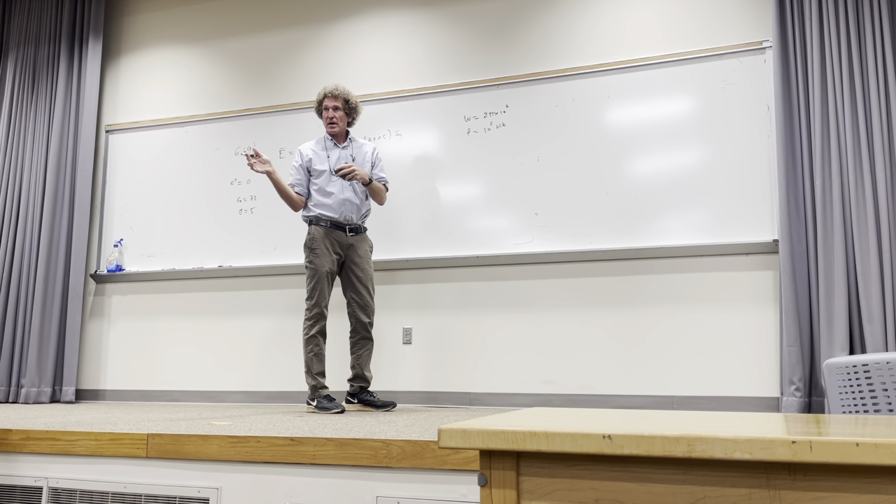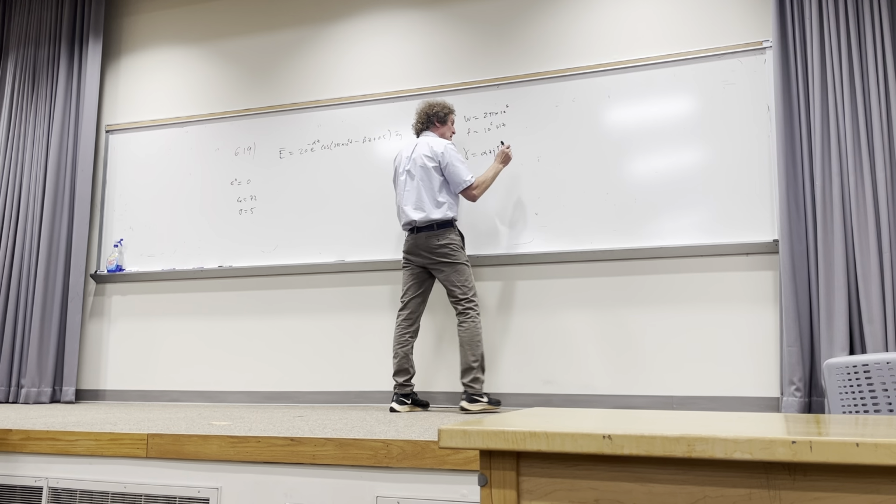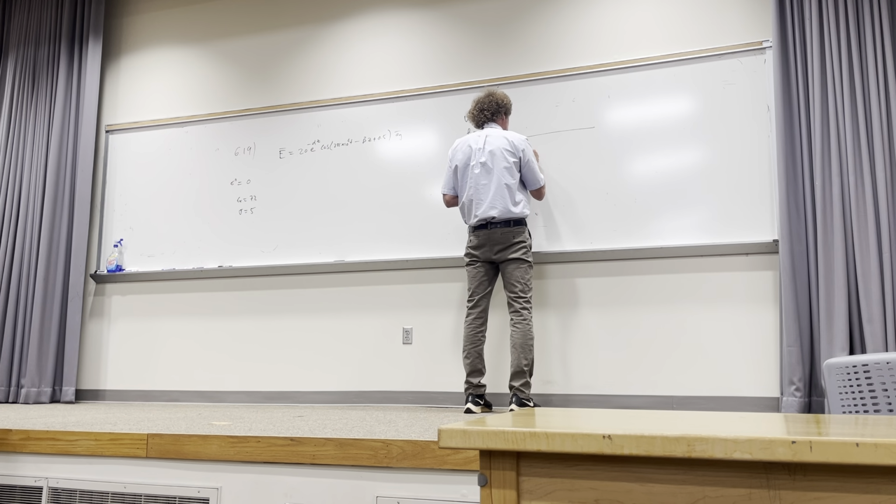All right, now after that, what I'm going to do is something fairly simple. When I take a look at the actual value for the propagation constant, which is alpha plus j beta here, that's equal to the square root of j omega mu times sigma plus j omega epsilon, right? Do you all give me that? Here's where we're going to see something. I believe Wentworth chose these values for a specific reason, but I'm going to see if I'm right about this.